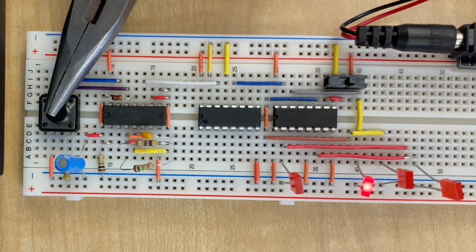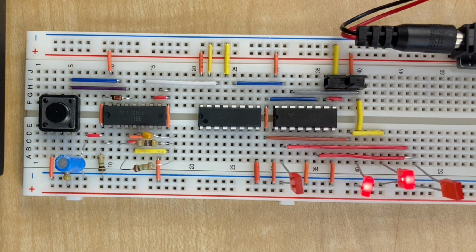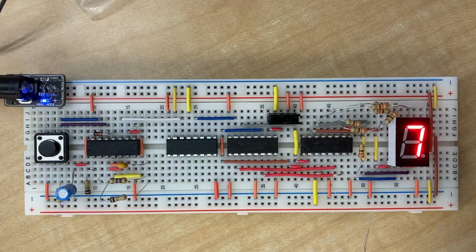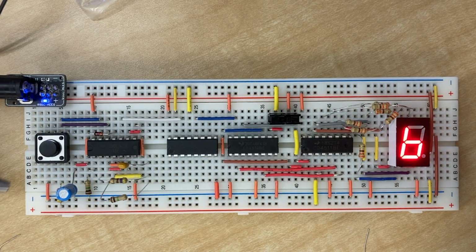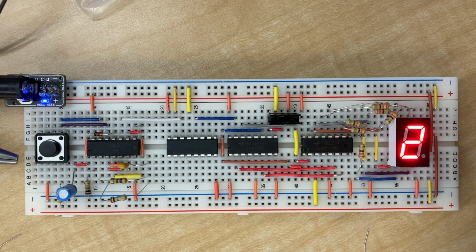Next, the newly modified clock signal is sent to the 4510 IC, which converts it into a 4-bit binary output. Finally, the 4-bit binary values are fed into the 4511 IC, which converts them into 7 separate outputs, which the common cathode 7-segment display is able to read. It is then displayed as counting from 0 to 9, either up or down, depending on the 4510 chip.